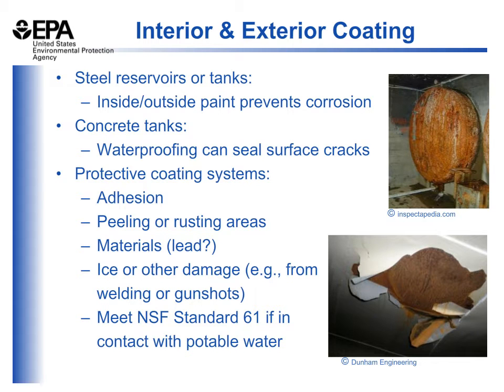Interior and exterior coatings in your tank are important for steel reservoirs or tanks. When steel is exposed to oxygen and moisture, it'll corrode, as we all know. If you think about your tank's exterior, there is a relatively uniform environment, but on the inside you may have some pretty severe conditions such as ice building up and scraping the sides of the tank, or corrosive conditions depending on the quality of your water.